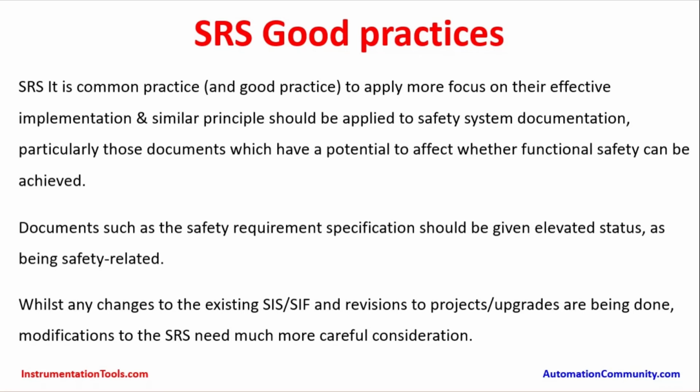So it is good practice to develop the safety requirement specifications during the engineering phase, test the instruments according to the standards, and document it. Documents such as the safety requirement specifications should be given elevated status as being safety related, and whenever changes to the existing SIS or SIF and revisions for project upgrades are being done, modifications to the SRS need to be given much more careful consideration.